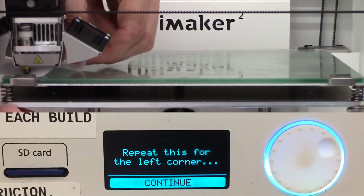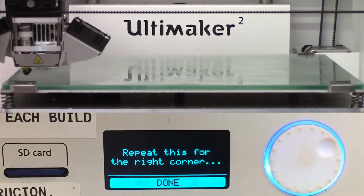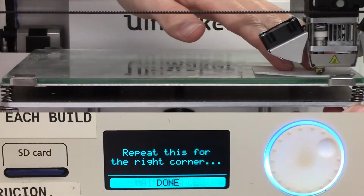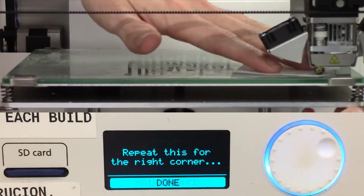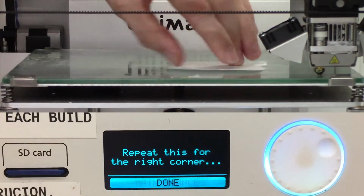And once we have that, we're going to go back to the wheel, press the button to press continue, and go ahead and do the same for the front right of the printer tray. It's important to be meticulous about this process, as most prints fail during the initial stages of printing due to the fact that the printed parts peel off the printer tray.